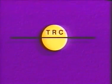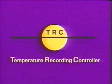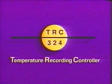The letters in this instrument symbol stand for temperature recording controller. The number of the control loop, if any, is shown in the bottom of the symbol. In a given process, there may be several loops controlling the same kind of variable, so each loop has its own number. Every instrument in a loop can be identified by the same loop number.